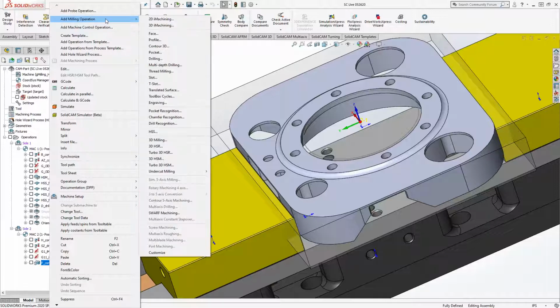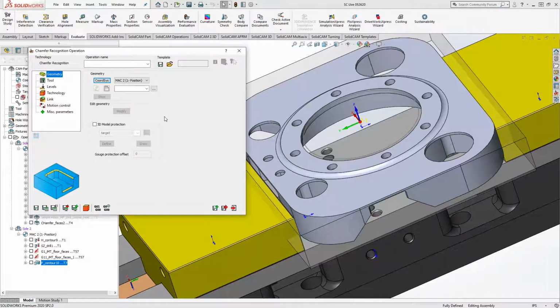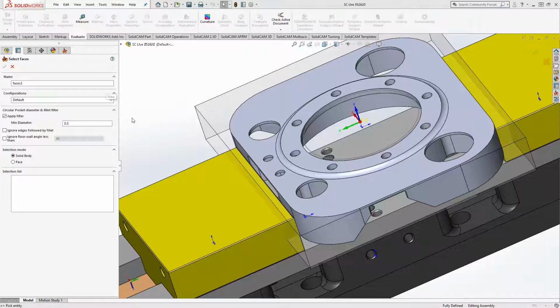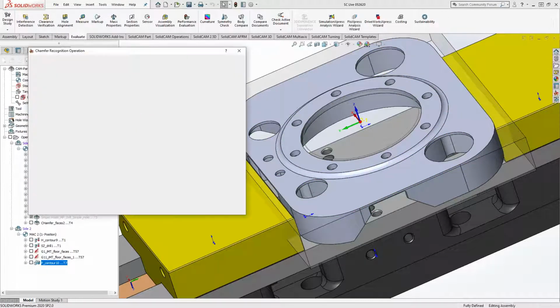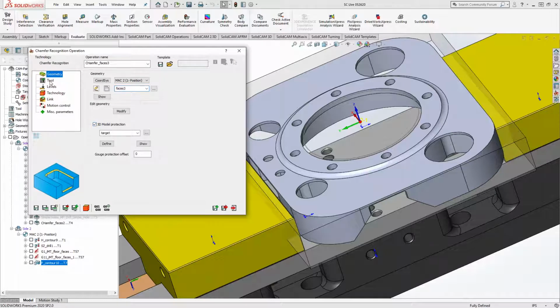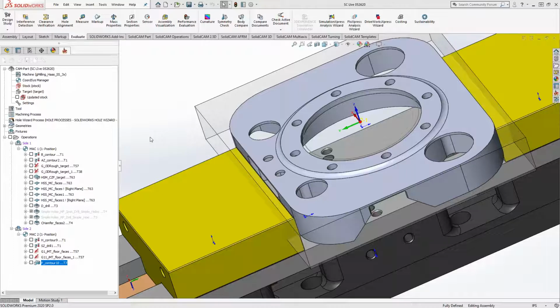Now I'm adding these as we go along, but again, you could have actually just done a save and copy, changed it to Mac 2, and then just reapplied it, or reselect geometries under Mac 2, depending on the toolpath. So basically just repeating what we did before. So in this section, I'll grab tool 4.